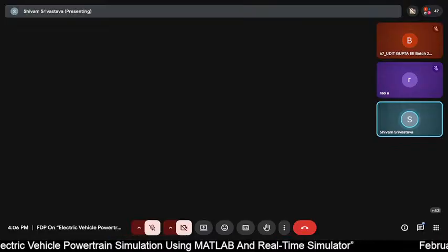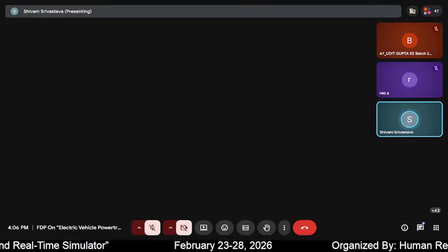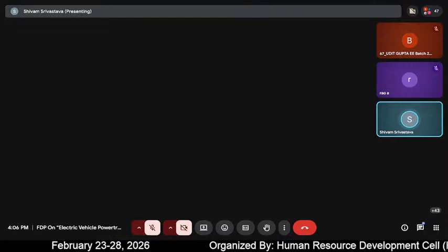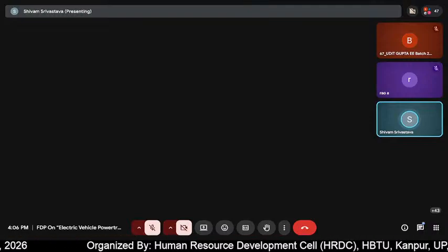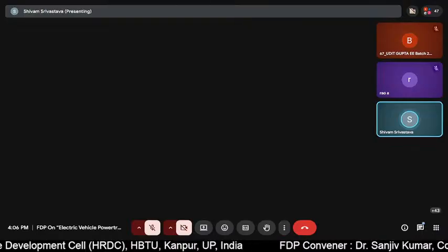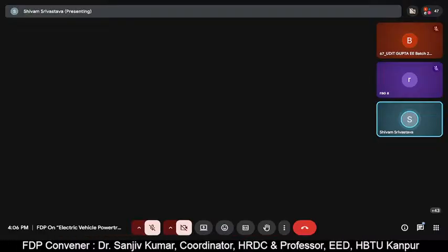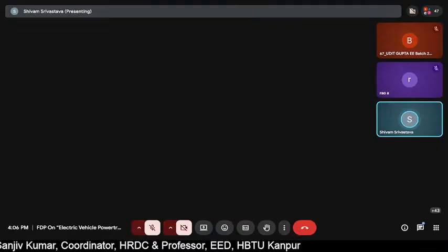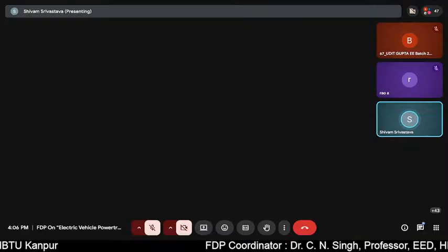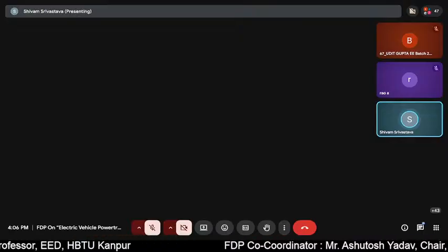So what you need to do is simply click on the install button present on the right hand side, and after installing this, whatever examples are associated with this toolbox are automatically added inside the example tab. As you can see, the second last option, the TI C2000 toolbox example tab, is available to me, and you can see the various examples associated with it, and these are all ready to use. You can click on any of the examples, and by clicking on open model, you are ready to use this pre-built example model inside the schematic editor,